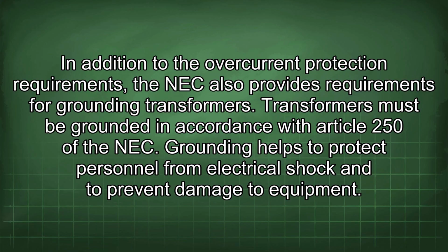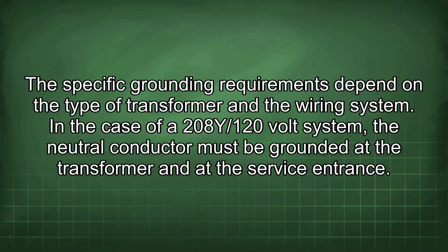In addition to the overcurrent protection requirements, the NEC also provides requirements for grounding transformers. Transformers must be grounded in accordance with Article 250 of the NEC. Grounding helps to protect personnel from electrical shock and to prevent damage to equipment. The specific grounding requirements depend on the type of transformer and the wiring system.